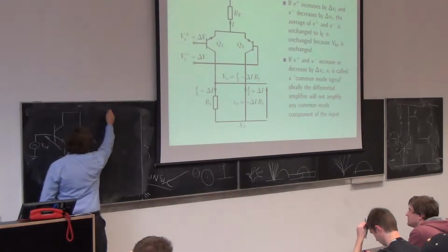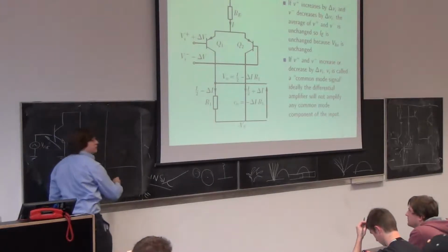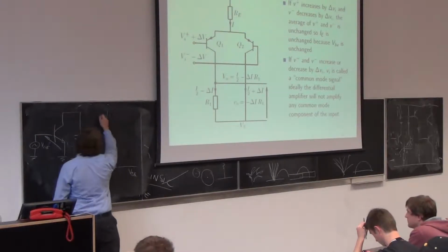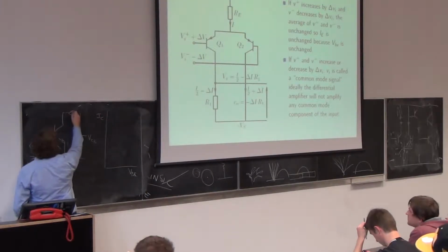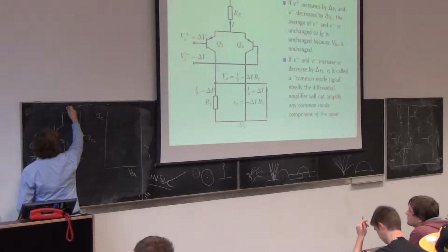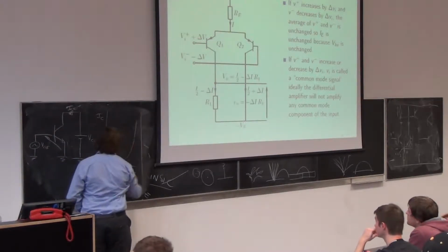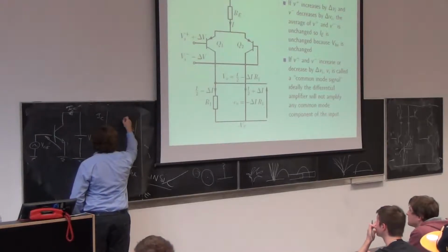The resulting graph that I will draw will be a transfer characteristic. So I'll end up with VBE against IC. I'll measure this current, and I'm going to get something like that, where this is exponential.